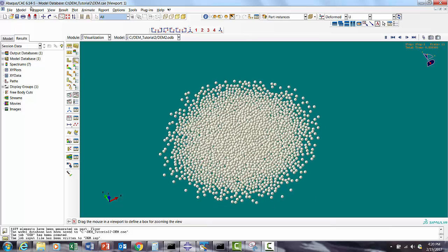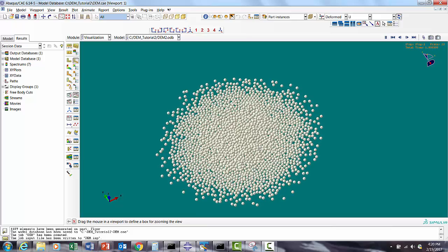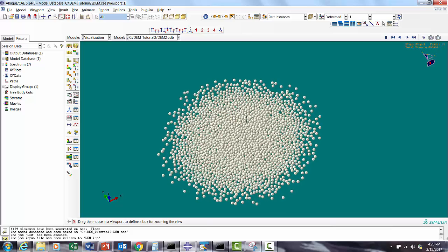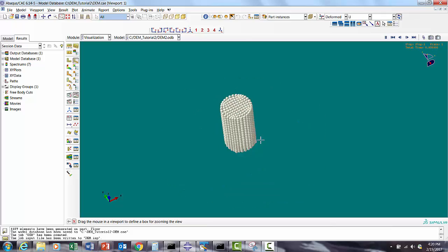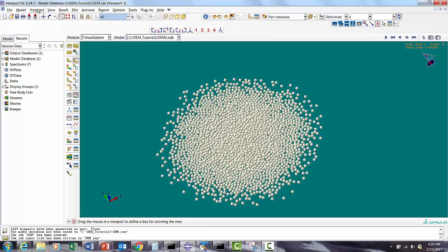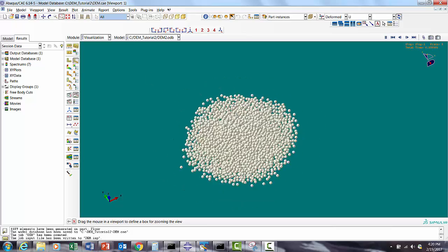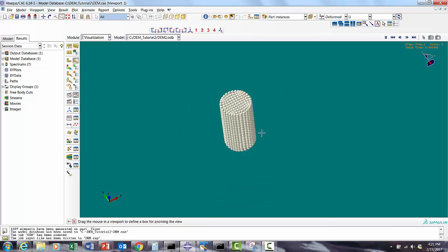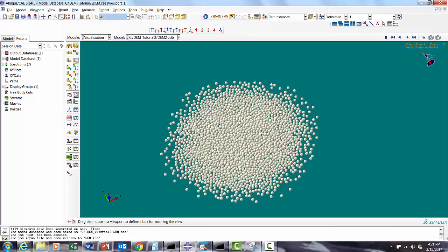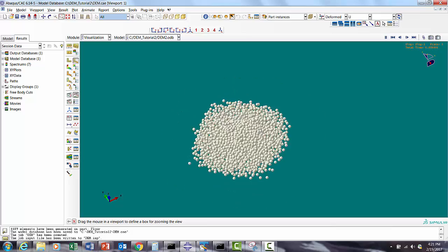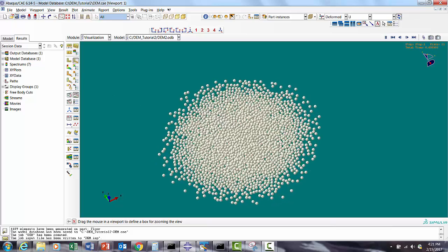We are going to use Abaqus 6.14-5. With Abaqus 6.16 there are a lot of advancements in terms of discrete elements, so you can use particle modulus, and also Hertz contact. We have some limitations with a lower version like 6.14, but we'll try to cover what we did. On my screen you see a bunch of spherical sand particles in a free fall under gravity, and we'll look into how we can model this. This is the problem we are going to model.